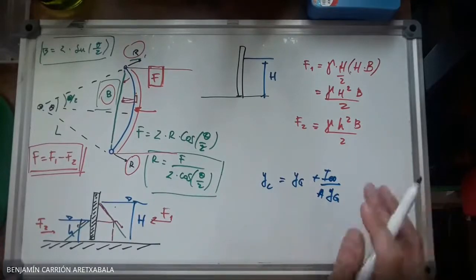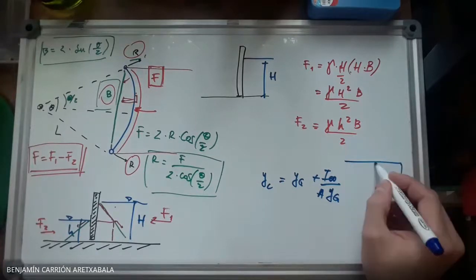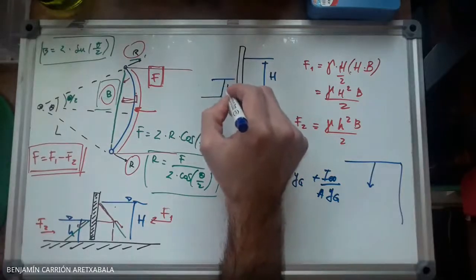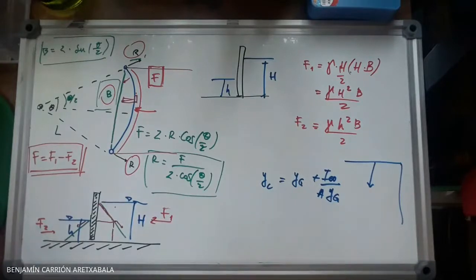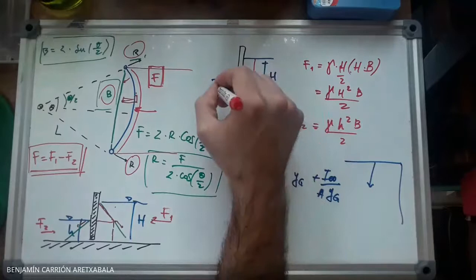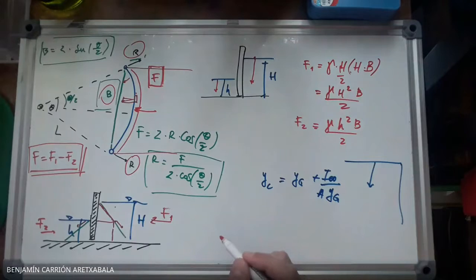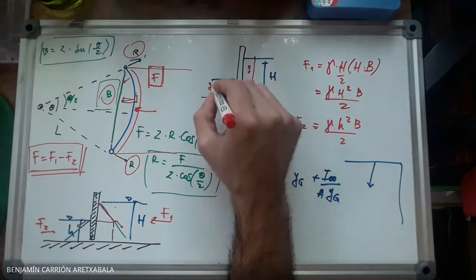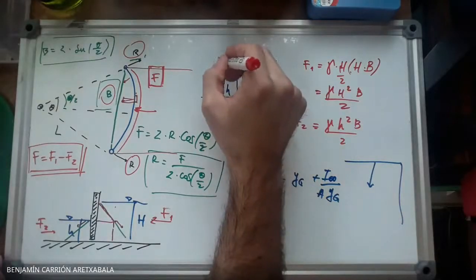But you need to realize, and I told you this in the last class, here y is measured from the free surface. So when you have this, you could have computed this one for 1 and 2, but both would have been drawn from different points on the vertical. So this yc would have been this distance, and this distance from the free surface, which is different on each side. Of course, you could have said, well, this is just this difference, h minus h.